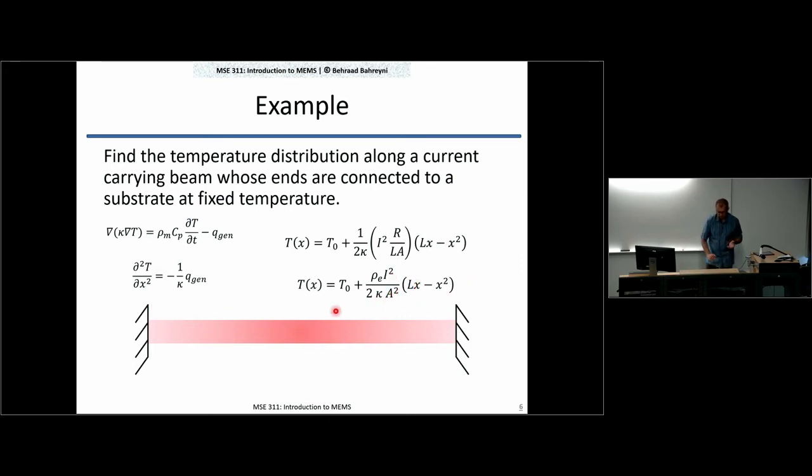Okay, so just a note here: convection is usually not a concern at microscales. The reason for that is, in most situations, your device is made of silicon and it is sitting on a silicon substrate. And for silicon, the thermal conductivity is quite high. It's actually larger than some of the metals. So the device is sitting on essentially a heatsink.